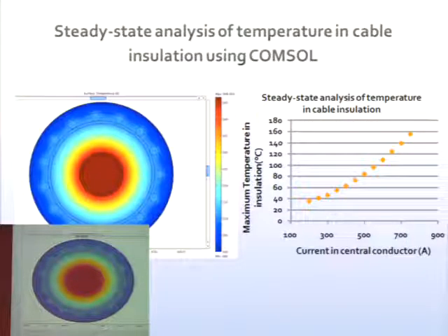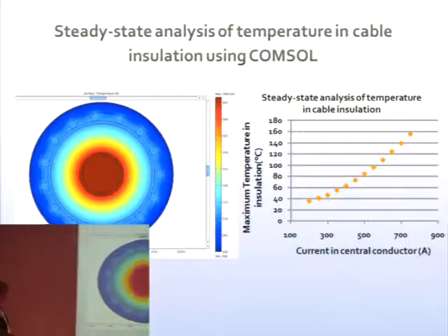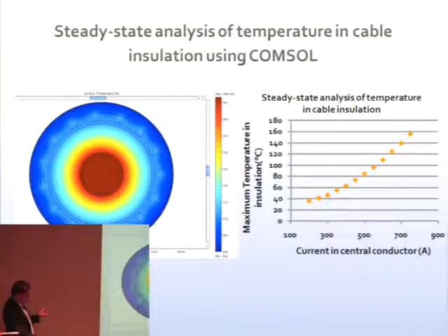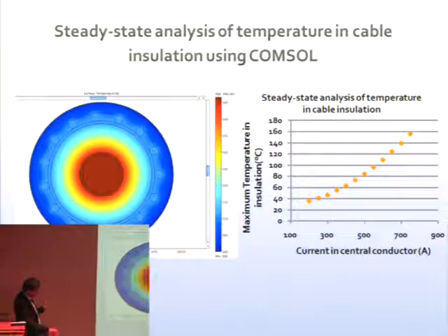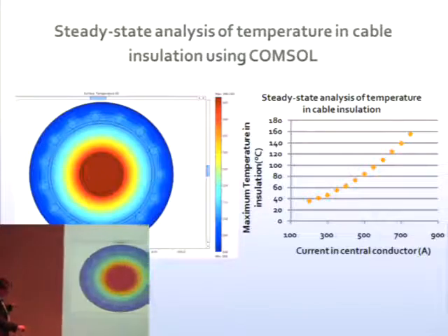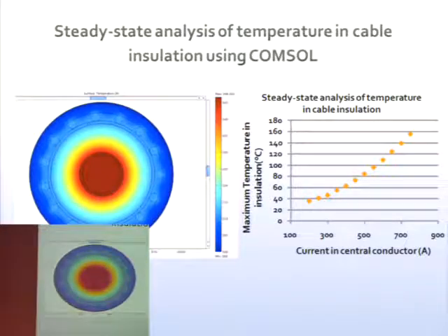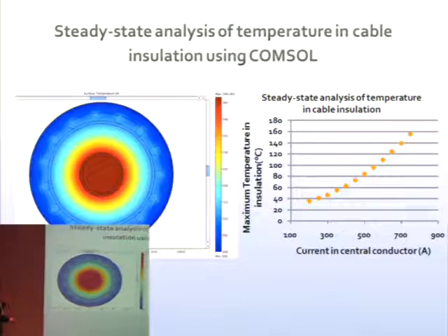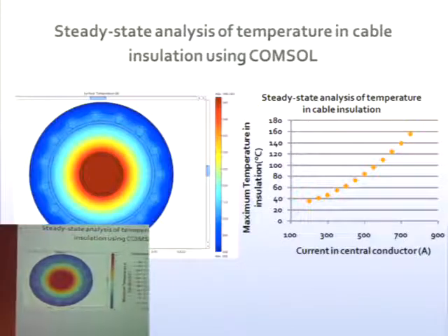And if you're telling me it's higher than the 25 degrees Celsius that I suppose, that's going to make this polyethylene hotter still. Yes. However, you have to limit the power dissipation to keep that temperature down. Well, okay. 90 C. I recognize that, and that means there's obviously a limit on what sort of current we can pass through this. Right. But I think for this particular cable, it was somewhere in this vicinity, suggesting that 60 degrees is not unusual.